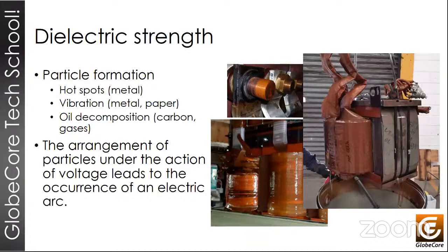The transformer is usually thought of or described as a static, stationary electrical machine. But in reality, there is a dynamic that involves certain kinds of motion, making a transformer subject to internal changes and pressures that can affect different parts of the device. So transformer vibrations are related to the current and voltage and load on the transformer. Changes in the temperature of the equipment also produce thermal expansion and contraction of some parts of the equipment, among other processes, and that can cause formation of solid particulate matter suspended in the oil. The aging or degradation of the paper insulation also generates furans. Problems like excessive heating or local hotspots generate suspended solid particles, and the degradation of oil allows the beginning of a coagulation process where small particles clump together and form larger particles, and that may even result in sludge later on. Next slide, please.